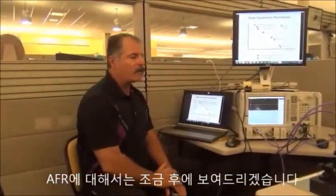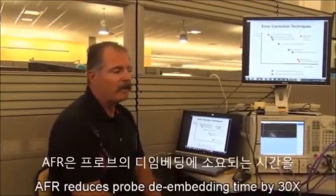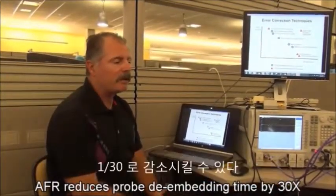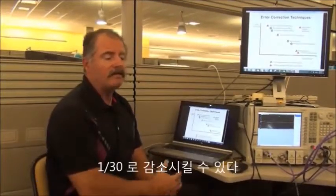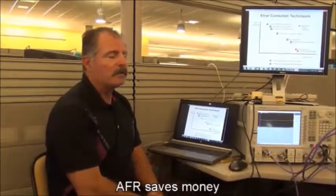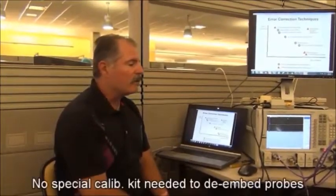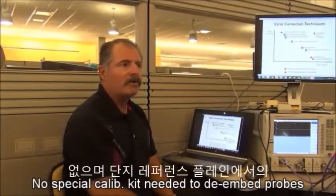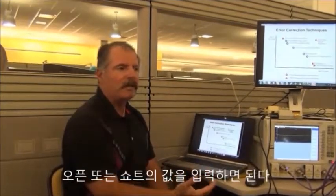The way that we're going to do it today with AFR is going to probably save on the order of 30 times the amount of time spent. A TRL calibration kit, once you design it, fabricate it, use it, it's going to cost, who knows, $5,000 to $10,000, and the measurement will take maybe a couple hours. With AFR, you don't need to build any special cal kit. All you need is to put an open or a short at the reference plane that you want.